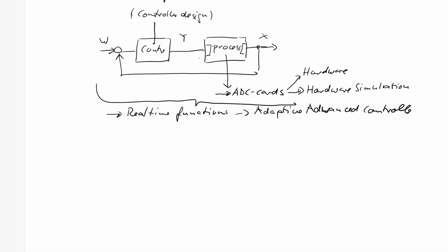With this menu point, then you can select simple controllers, but of course all other up to adaptive versions we will discuss in this lecture. So with this big menu point with many settings and knobs and buttons and parameters, don't be confused with this window. I show you which settings you have to do to get a simple PI controller running with a simple process. Okay, let's start the program.